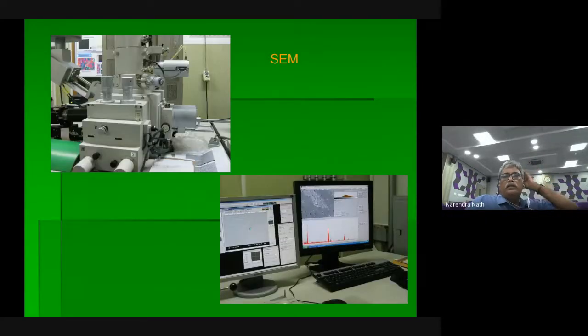You should cut at low speed. If it is high speed, because of the temperature, transformation will take place in the material right there. Cut at very low speed and monitor very carefully. You have to take 20 mg specimens and collect a few, say 5 or 10. Then weigh them, choose the one closer to 20 which is flat, and use that for DSC studies. That gives a nice result. And this is scanning electron microscopy.